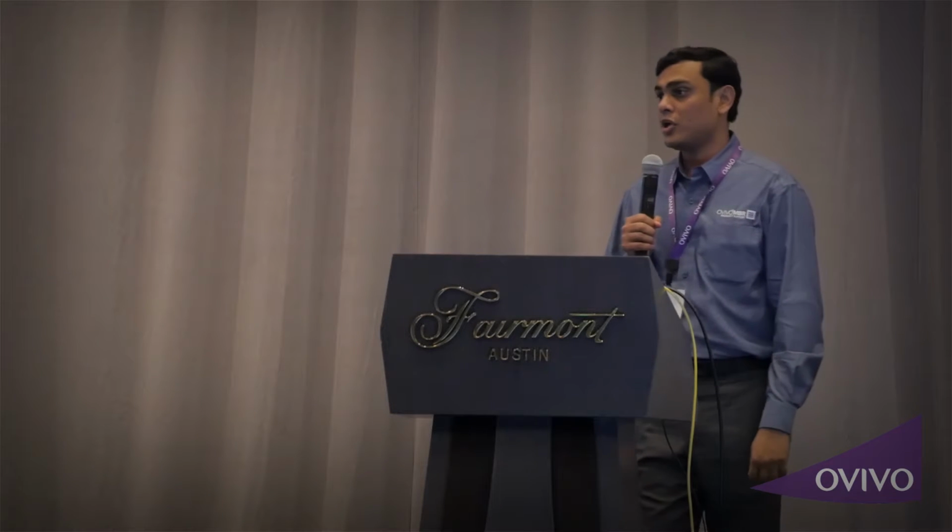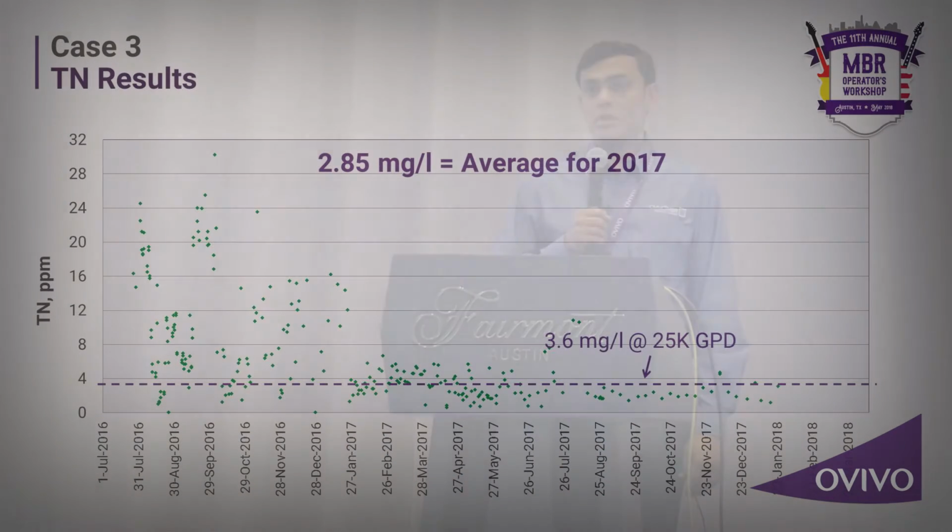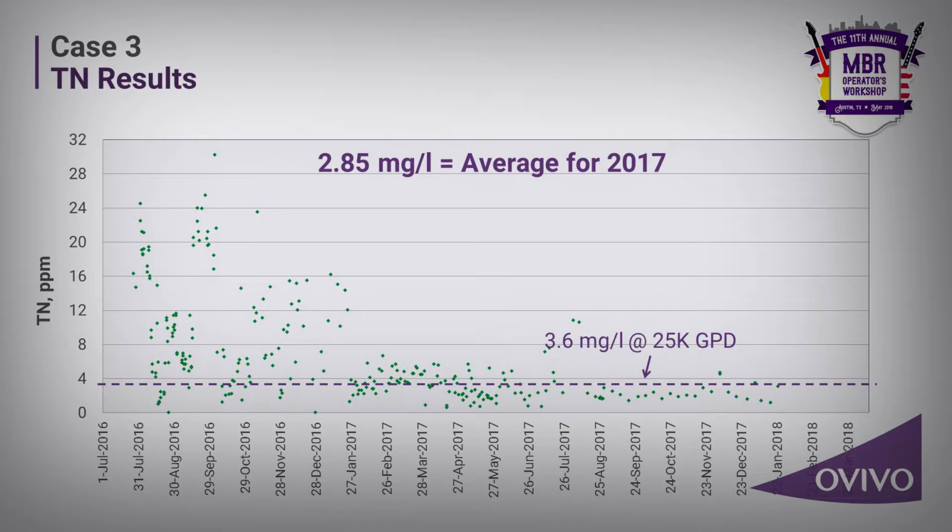That's where the flow was coming in high and it was a single tank system. And when we introduced the pre-anoxic tank, the customer started getting TN within the limit. The average TN here at 25K gallons per day was 3.6, which is the limit. And in 2017, this number was 2.85 ppm in permeate.